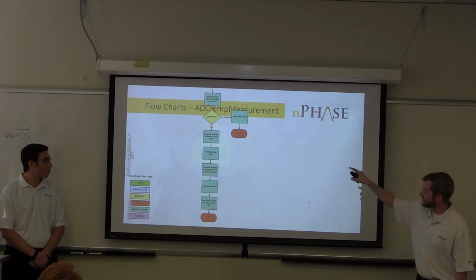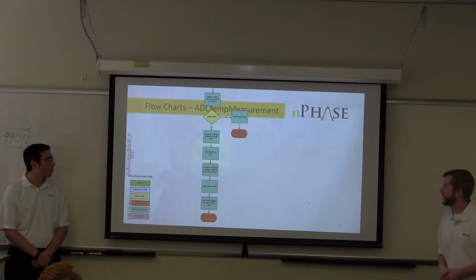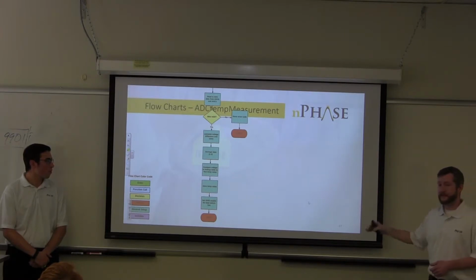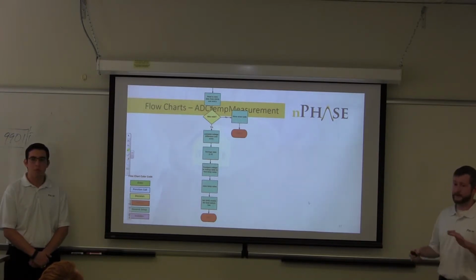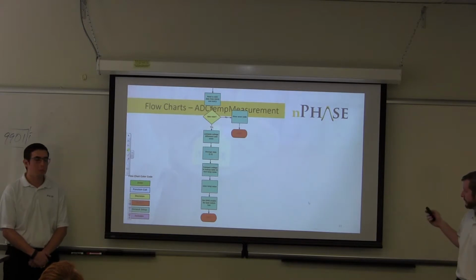Once we have our 3 measurements, we're going to average it out. We're going to be storing that value, and then we're going to disable the load switch again so that the Wheatstone bridge is unpowered. And then returning.